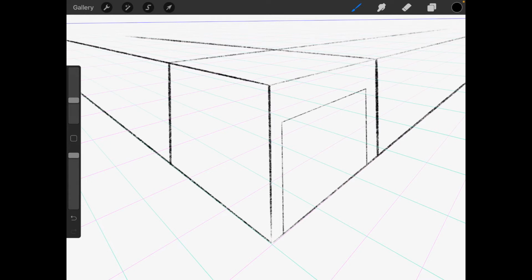Okay, but I don't want the extrusion to go all the way through. So what I'm going to do is set up an endpoint for the extrusion. I want the extrusion to go up till here, right? So from this point I will take the line backwards and stop it at that endpoint.